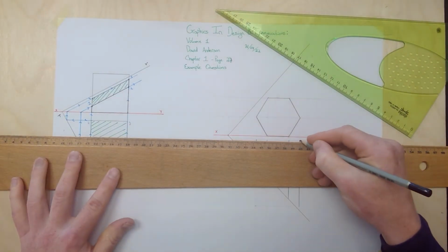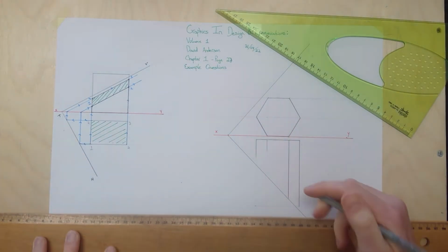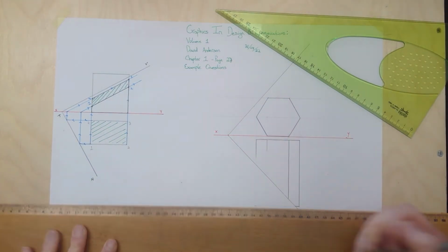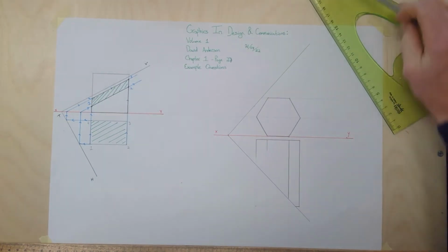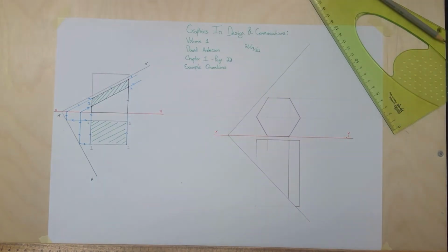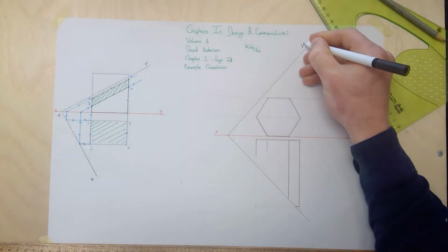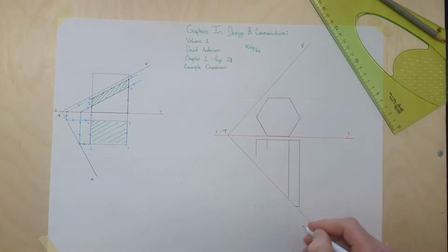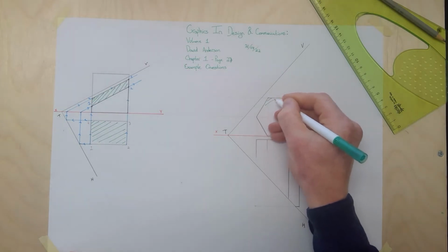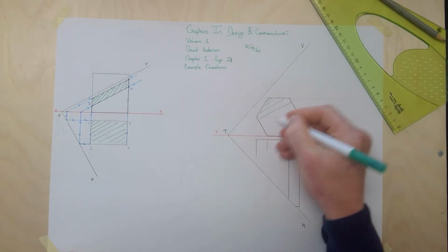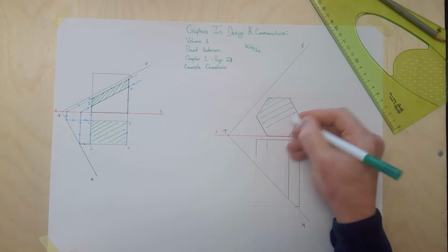A portion of them lines, and after about a portion of this line as well when I actually do my cut. But that's how it's starting anyway. And I'm just going to label my stuff in like I always do. So VT for vertical trace, and then HT for horizontal trace. Okay. So in this view is where we can see the cut shape of the surface. So this view here that I've done my green hatching in.